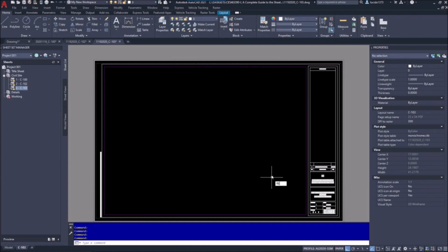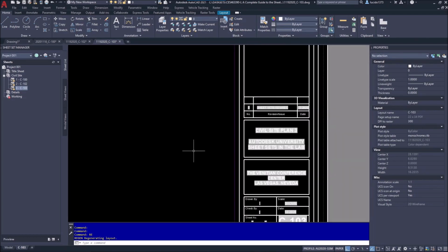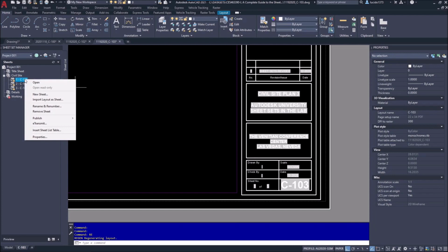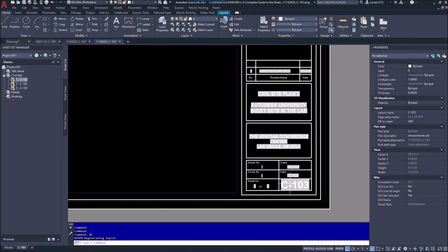Okay. And you'll see how that changed. So we have all these drawings in here. We've got our template created, so now we know it works. All of this data is continually carried over. The only differences are the sheet properties, which are controlled by each sheet, which is actually the title of it, the description, and the drawn by and the checked by. We didn't fill any of those. The total number of sheets is controlled by the sheet set.